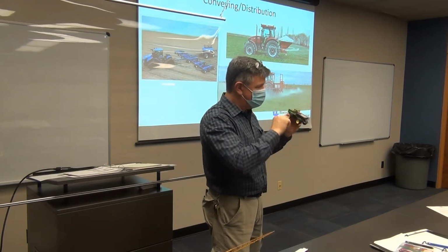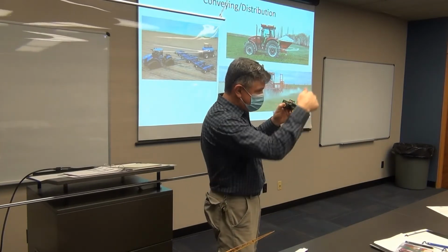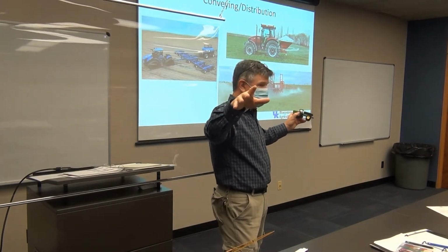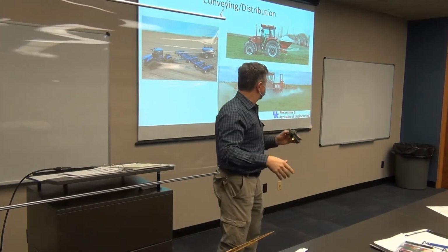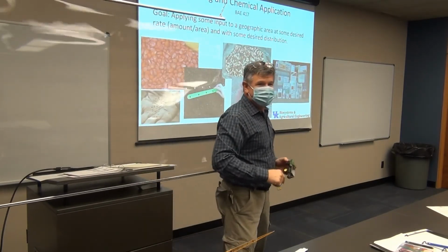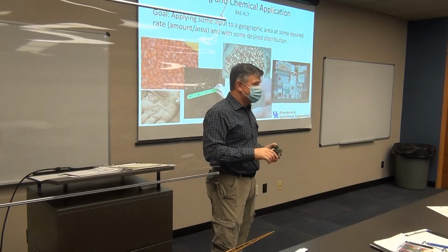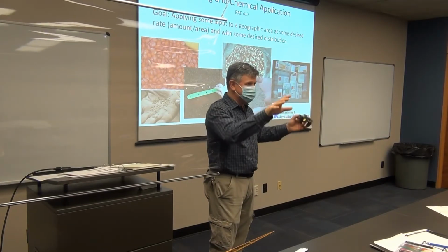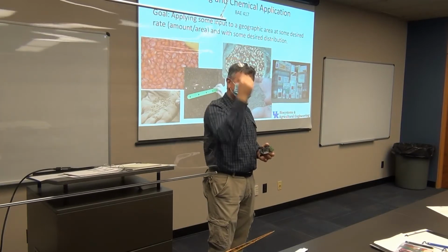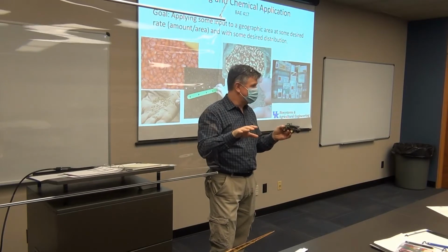So the material gets pulled out of the machine. There's a belt in there that will pull the material out the bottom of the bin, drop it on those spinners, and then it just flings it out where it goes, okay? So think about all those particles. That's that machine in the upper left. Are all those particles the same size? You look at it, no. Are they all the same density? Probably not. Will they all fly the same direction, the same distance, and terminal velocities and all that kind of stuff? There's a lot of thought process that goes into how we get this out there, how we get a decent distribution.